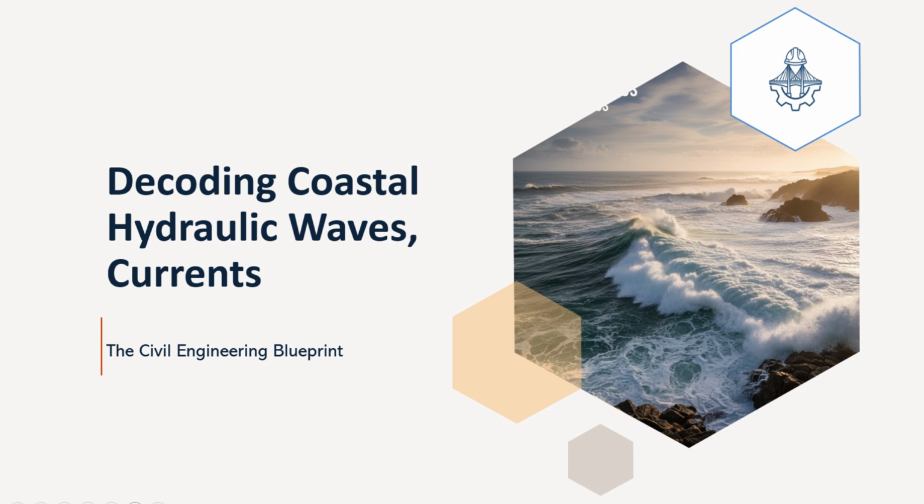Under waves, understanding where the water itself actually moves, not just the waveform propagating across the surface. Okay. By taking partial derivatives of that velocity potential we found earlier, specifically with respect to x, the horizontal direction, and z, the vertical direction, we can directly derive the horizontal vx and vertical vz components of the water particle velocity at any point within the water column and at any time t. These equations tell us the instantaneous speed and direction of individual water particles as the wave passes.